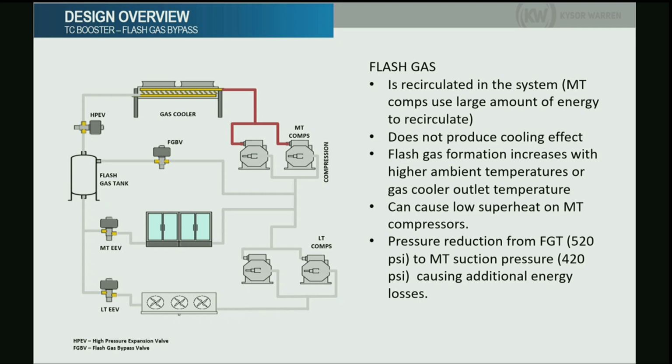It will be only vapor. So if that is the case, that we have only vapor, we are not condensing, so the unit is not called condenser. We are only cooling the gas from high temperature to a lower temperature, but it's still vapor or gas at the outlet. That's why it's called gas cooler. And that will be cooling the gas only when you are in high ambient temperature conditions, when you are above the critical point. So 100% vapor?